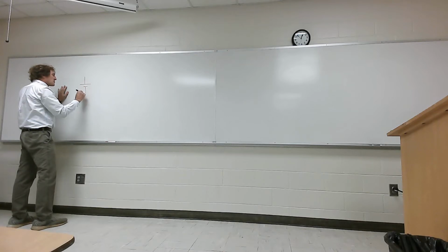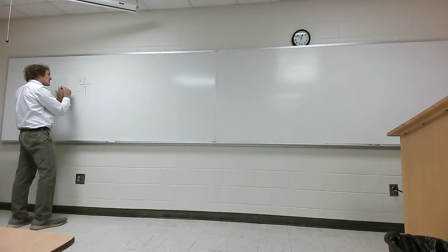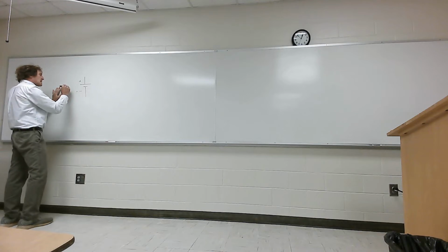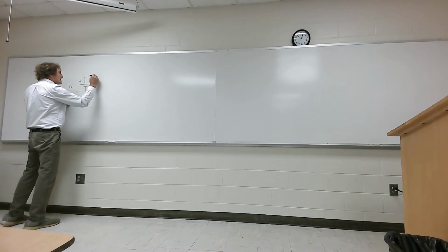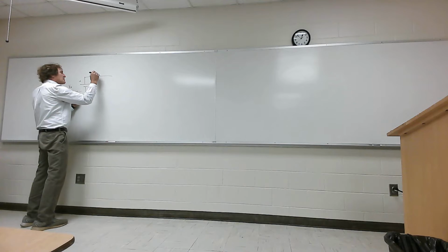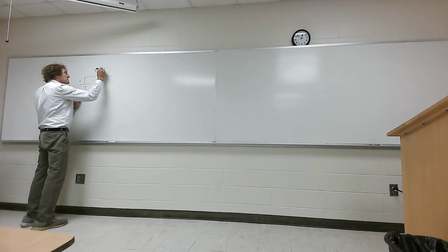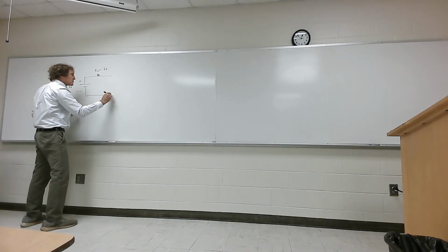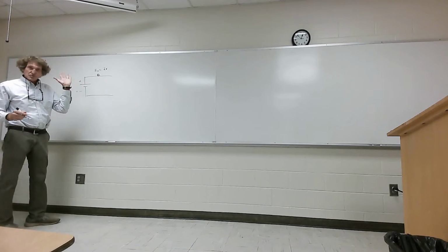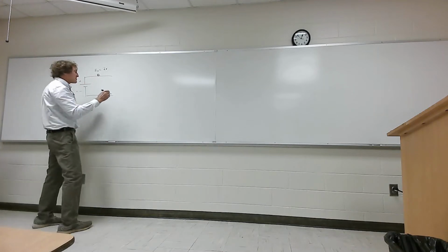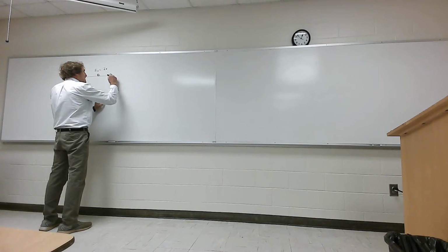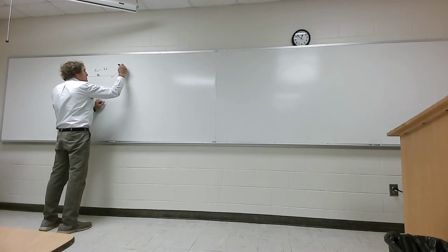I'm going to start with just a battery here. We're not going to have a pulse, and this is going to have some value V0. Then I'm going to make the source impedance RS equal to Z0, and the reason is it'll prevent any kind of bounce from the source side. It'll get too complicated if I don't do this. Here's my switch at t equals 0.